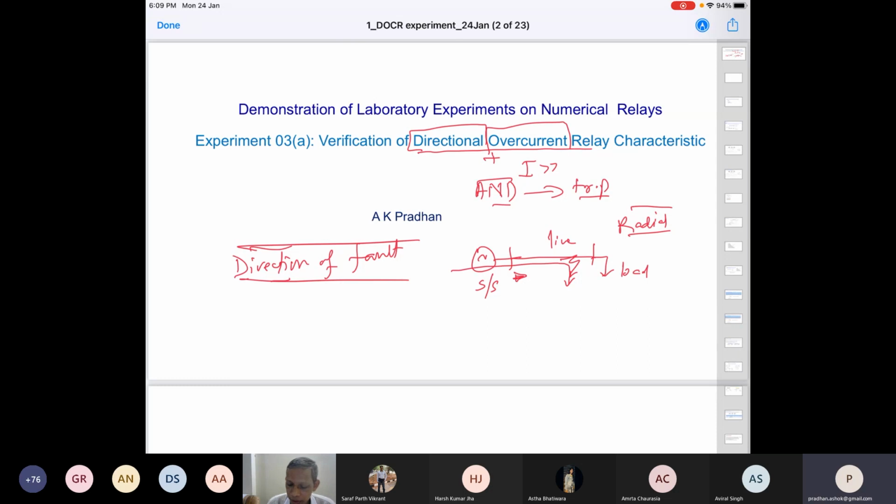But that is not always the case. See a situation in a high voltage system like 132 kV, 220 kV, or 400 kV. Many such systems, including if you go to our Kharagpur substation outside the DVC substation, 400 kV system. A transmission line can be interconnected, like in the India grid, where we have a 400 kV loop. This is a 400 kV loop system, a ring system. Similarly, a 765 kV ring system also.